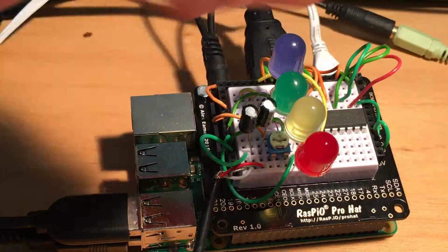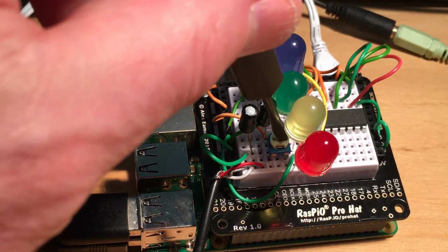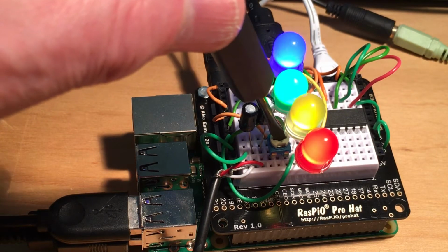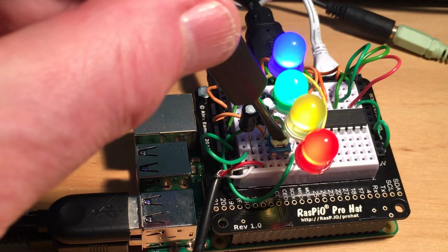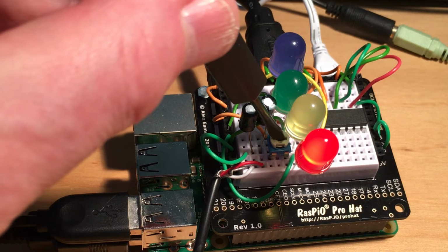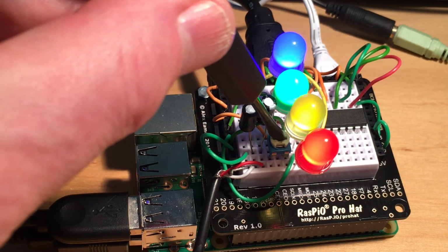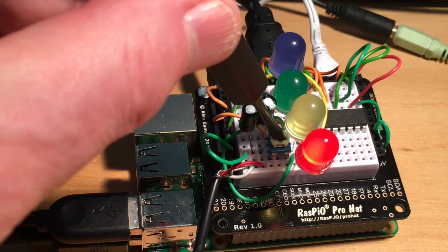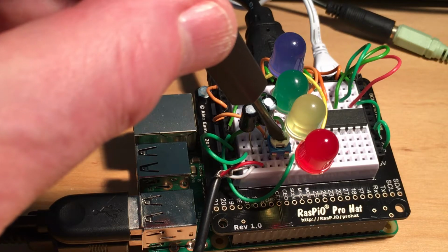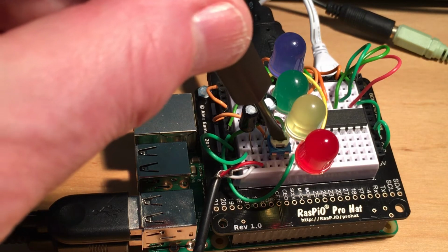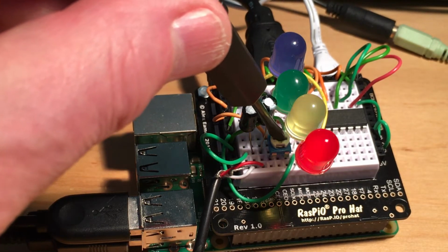Now I've got a small screwdriver here, and what I'm going to do is to put it into the potentiometer, which is just lurking underneath the LEDs here, and if I rotate that, you can see I can turn all the LEDs on. Now if I rotate it very slightly clockwise, you can see that one by one we reduce the LEDs. First of all, the blue one dims, there it goes, then the green, then the yellow, then the red. It's not a very big range because we haven't got a very big audio signal coming in here, so the sensitivity control has given a fairly small range to this LED bar graph that we've got here.